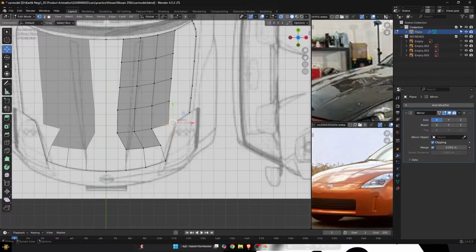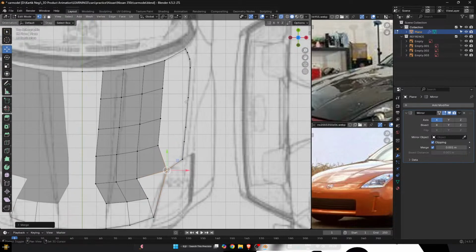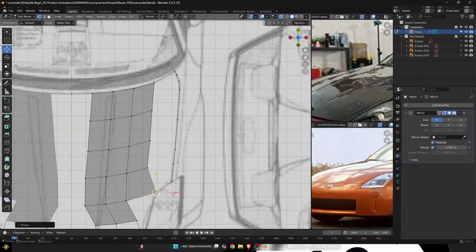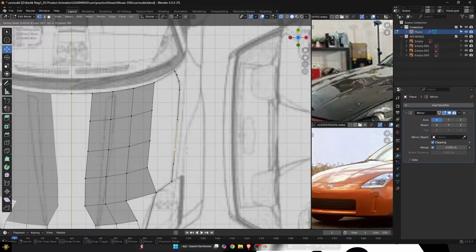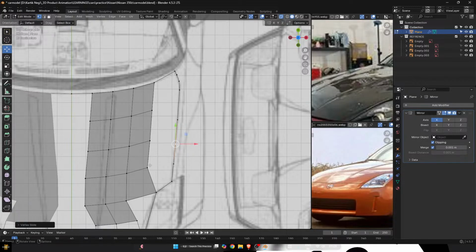When we are in object mode, we can make a new collection by pressing M. But when we are in edit mode, just select them and press M, and there are a lot of things you can do with these vertices. So we are going to merge them at last. The one which we selected last is the place where it is going to join itself. But you see over here, there is this problem. Just double click G to fix it. So this will be connected to this, to this, to this, but we don't have edges for them.